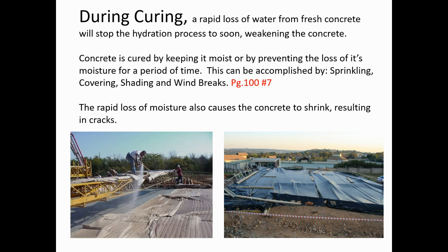If it's going to be really windy, sometimes you have to cover it up and shield it from the wind and shield it from the sun. So it's all about letting the water do its thing. If the water's not there, your concrete is not going to cure properly.